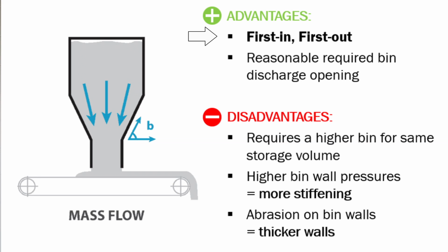With mass flow, the big advantage is the first in, first out discharge pattern, where all the material is in motion during discharge. In particular, when we are talking about a difficult flowing material, it is often better to keep it in motion rather than let it sit still.